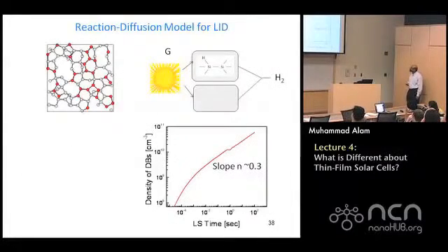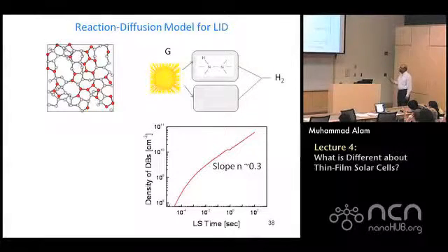The basic idea is this: amorphous silicon is not crystalline, it's a random structure, and many of the bonds are essentially not saturated. And so you need to passivate them with hydrogen. If you bring in hydrogen, that ties them up, and then you can have good performance. But as soon as you put them in light, these bonds begin to break, and something that you make easy also breaks easy, right?